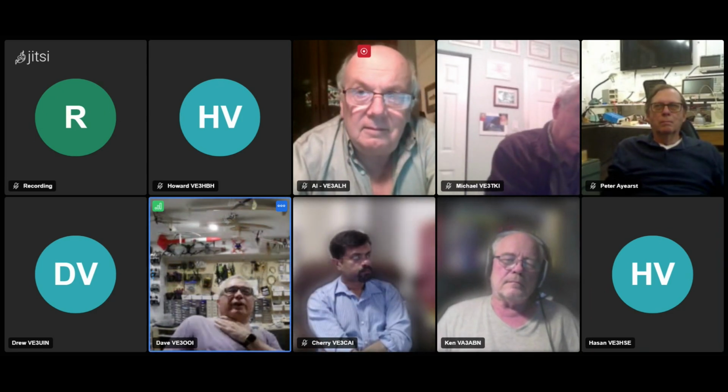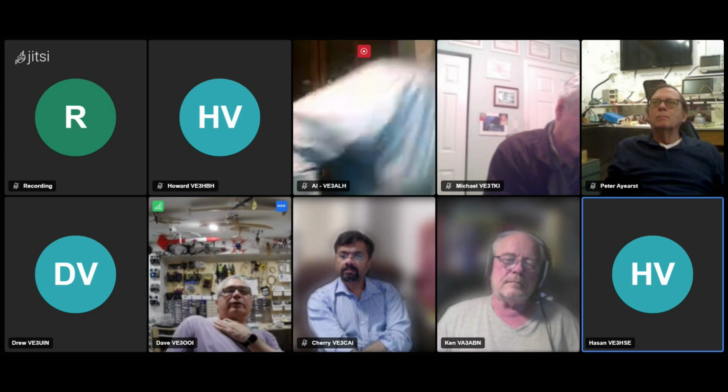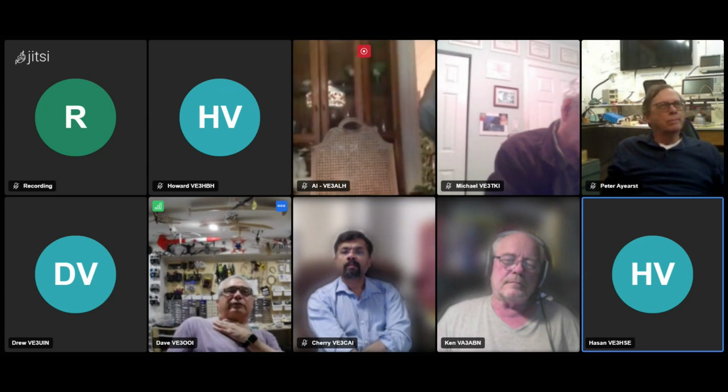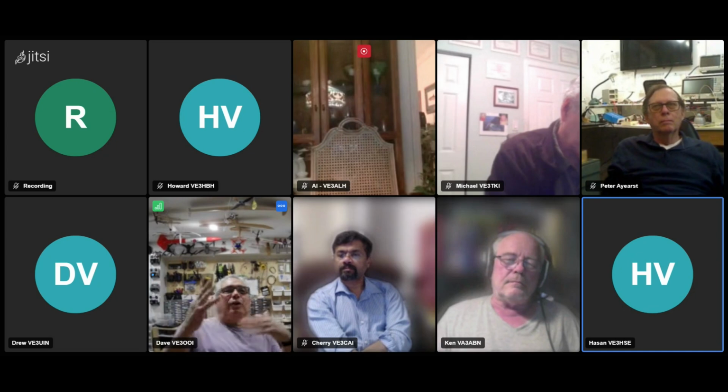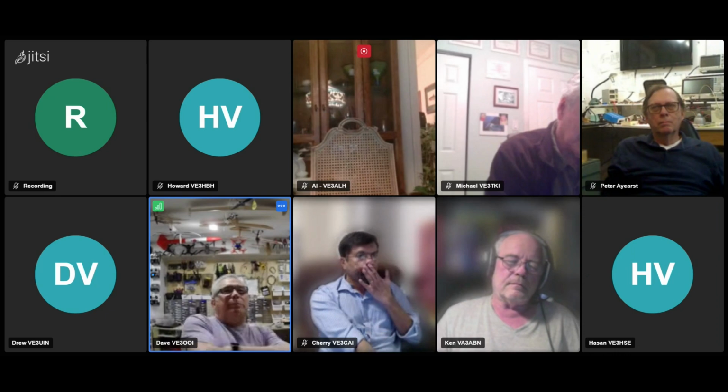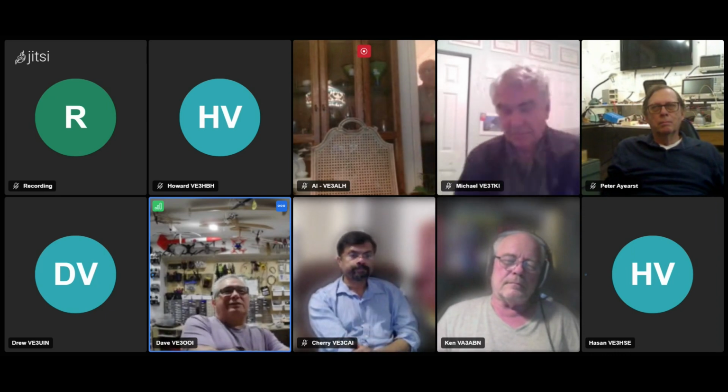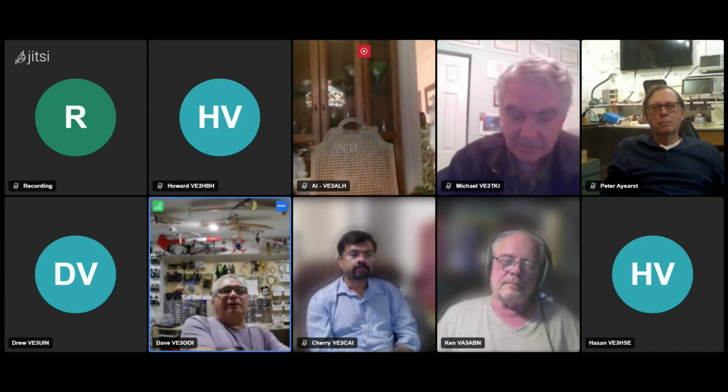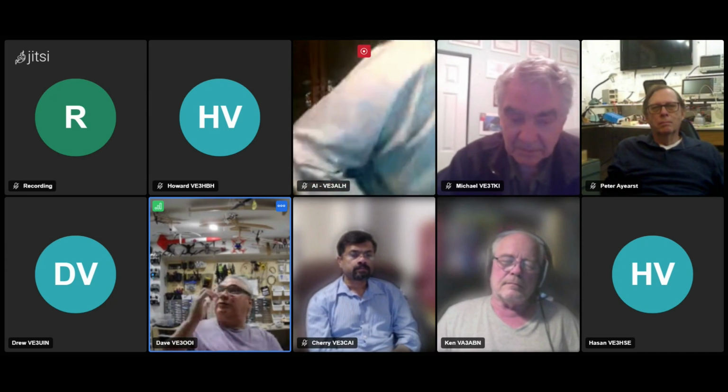Yeah, and I found, Hassan, just the way you screw on your SMA connector, if it's not tightened to a certain level, you see all kinds of stuff in the spectrum, and that's why I think you see people with torque wrenches when they're fastening their SMA connector, just to reduce all that noise. That's right, the IMSA guy does that, and I saw that on his webpage.